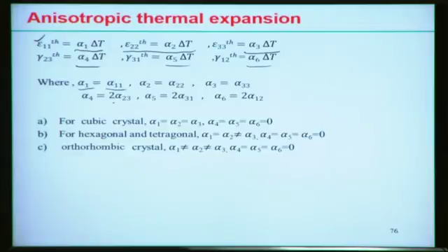Since it is a shear component, we multiply by the factor 2, the way we introduced in case of normal strain and thermal shear strain. Similarly, we introduce that effect in terms of the expansion coefficient.